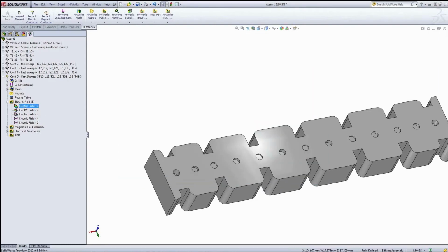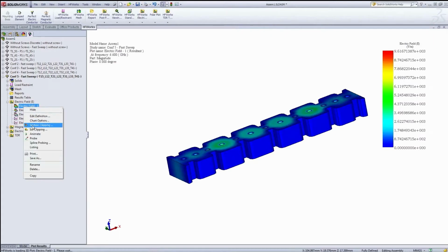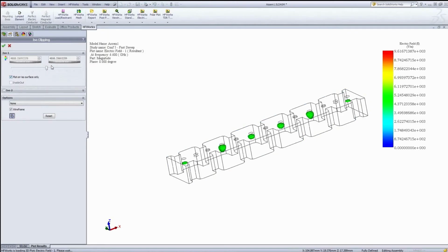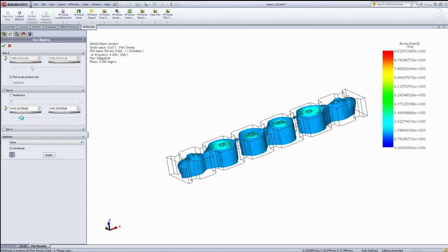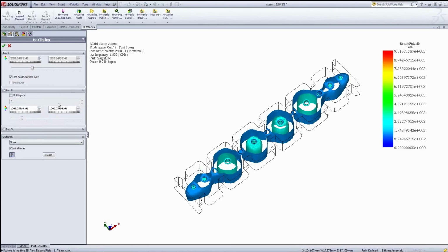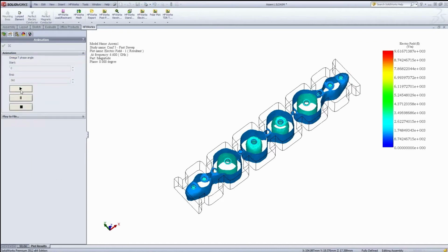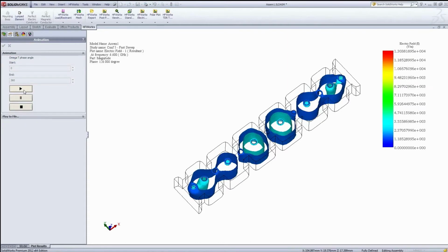So I can look at the field in different modes. I can do these kinds of plots. I can do section, etc. I can go and do isosurfaces if I wanted to. So I can just do isosurface only. I can play with the surface value and what are surfaces of equal value. I can do 2 of them, up to 6 of them if you wanted to. So these are 2 different surfaces. Isosurfaces keep adding. If you wanted to look at this, you can animate it in isosurface to see how these surfaces are propagating through the model.